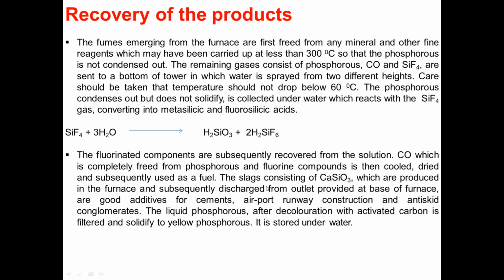So this, because it contains silica and it has calcareous properties also, can be used as an additive for cement, airport runway construction, and anti-skid conglomerates. Then the liquid phosphorus, after decoloration with activated carbon, is filtered and solidified to yellow phosphorus. This yellow phosphorus is stored under water because it is highly ignitable.